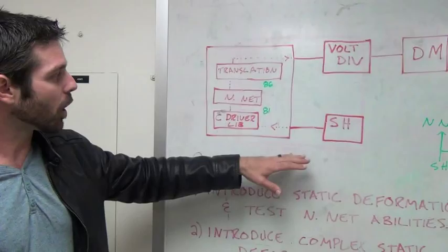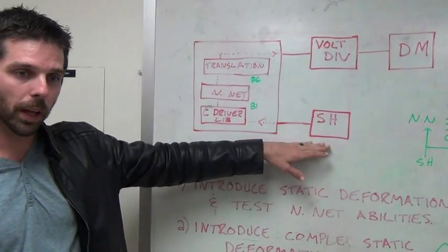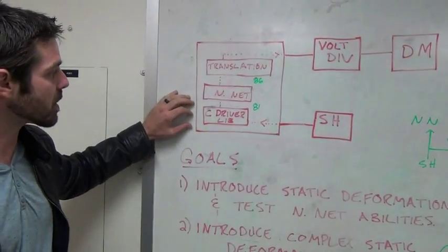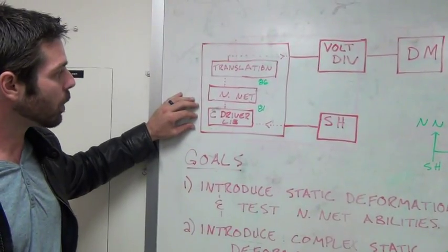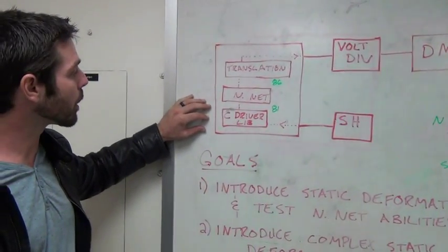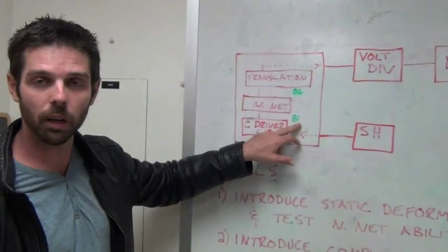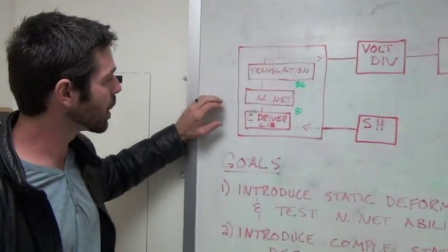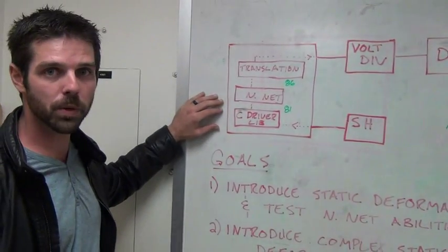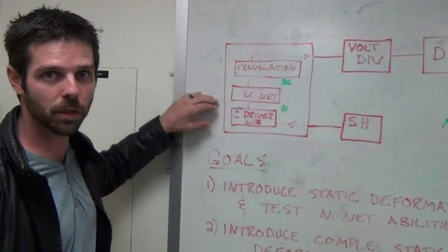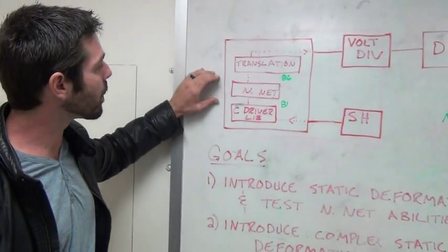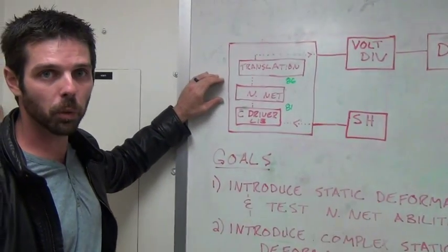But the Shack-Hartmann camera that we're using is a Thorlabs camera. It comes with an existing C driver library. We have used that driver library to create a two-dimensional array output of 81 floating point values. Those floating point values represent the z-axis deformation of the incident light. That data will be fed into a neural network.